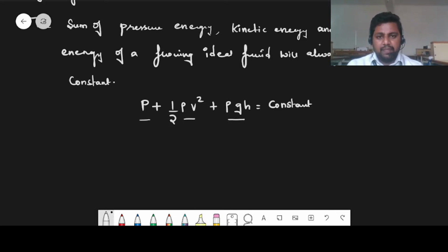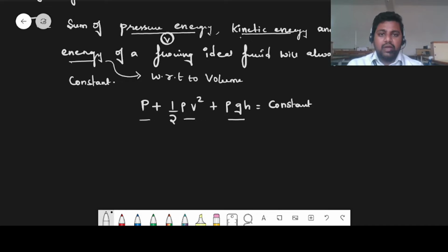We are not talking about pressure energy alone or kinetic energy alone or potential energy alone. These are analyzed, always remember, with respect to volume. That means pressure energy per unit volume, kinetic energy per unit volume, potential energy per unit volume of a flowing fluid will always remain constant. That is the reason why instead of writing mass, I am writing density. I hope you are understanding this equation.